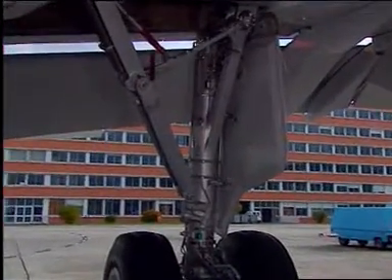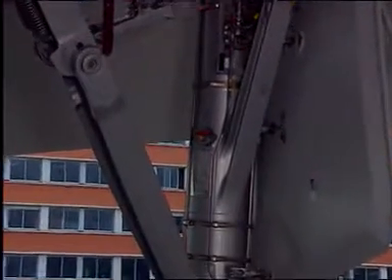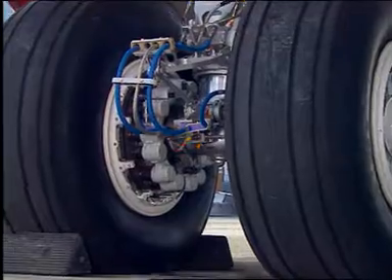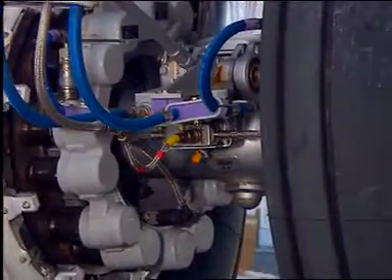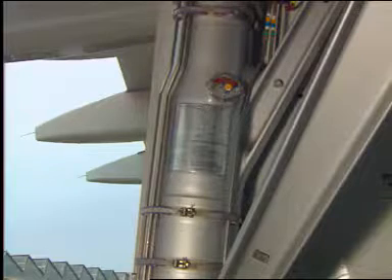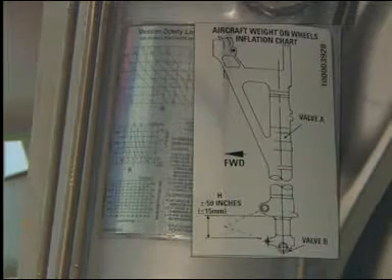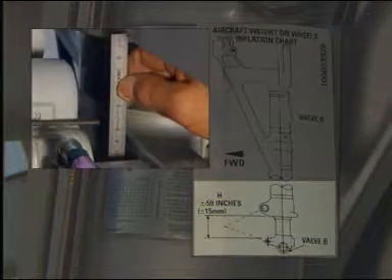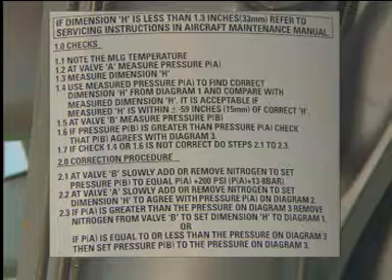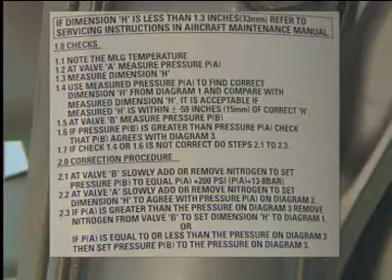During this procedure, actions will be made on the top charging valve, also called valve A, and on the bottom charging valve, also called valve B. A placard located underneath the top charging valve gives you a summary of the information necessary to perform this procedure. It consists of a gear schematic which shows you where you have to measure the height h. A summarized actions list which presents the main points necessary to perform the dedicated procedures.